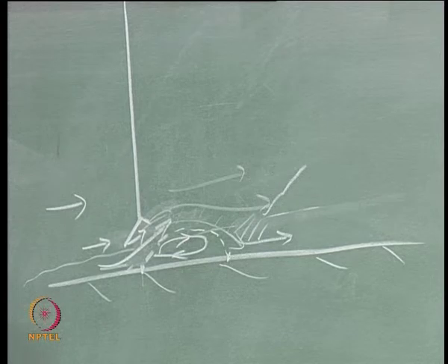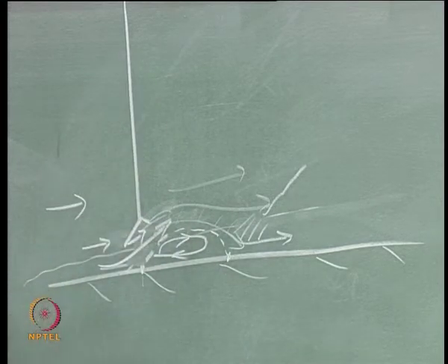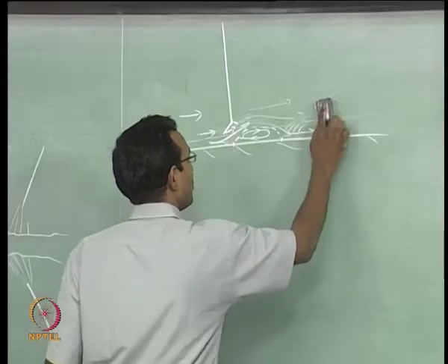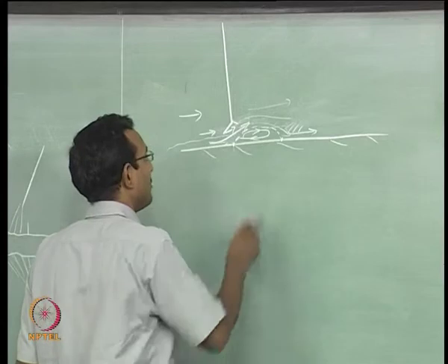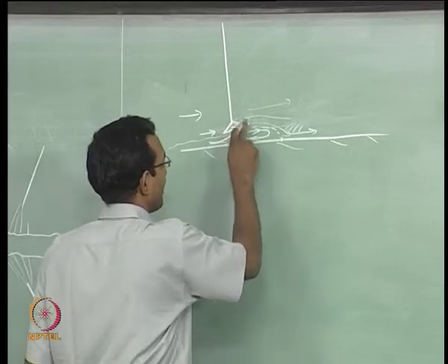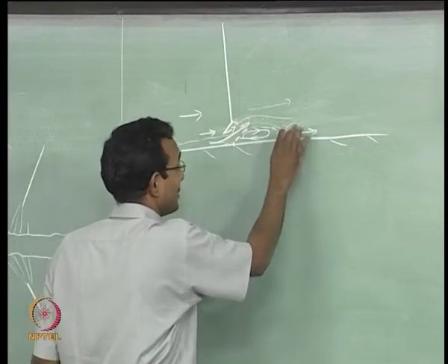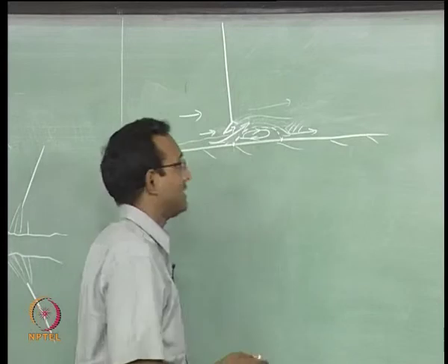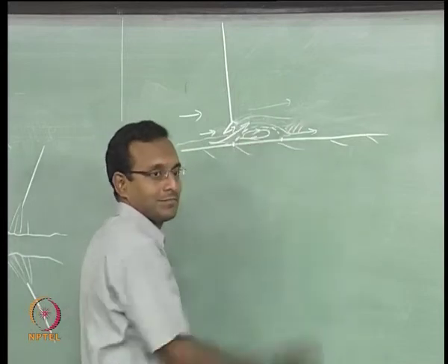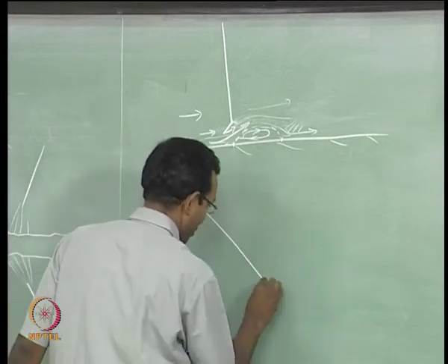This is the case not for a normal shock problem, but an oblique shock problem. For a normal shock problem, there will be no shocks formed downstream. But if it is a transonic zone, if the Mach number is close to 1, then you will still see the expansions and compressions if you go look at some particular density map or something. You will see that the density decreases and increases again. All that you will see. I will pick another case where it is oblique shock reflection on the wall.